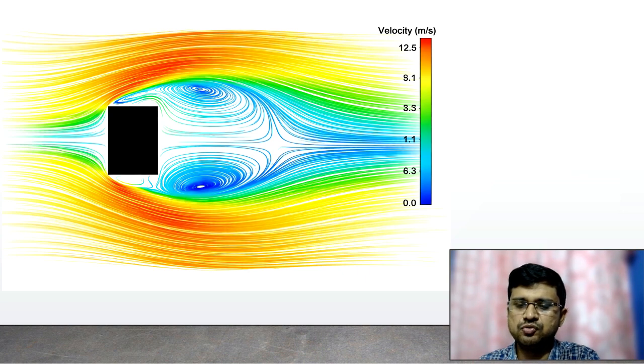Now, this is the top view of wind flow. Wind is coming from the left side. Here wind is coming from this side, and these 2 points are the wind separation points. At these 2 points, wind is actually detaching from the building surface. And here you can see in this particular zone, the wind velocity is quite high. As per Bernoulli's principle, if wind velocity is quite high, it is obvious that there will be a significant drop in wind pressure. So there will be suction in this particular zone just after the separation point.